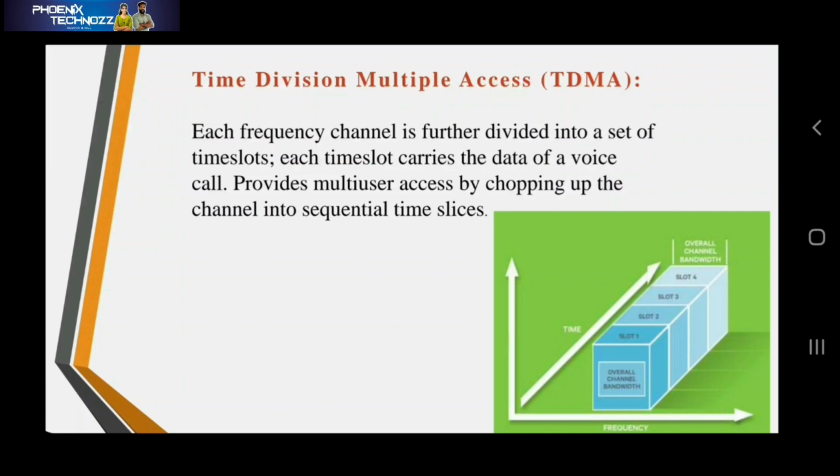So here also the multiple access interference can be avoided by allocating the communication resource in different time slots, but for the entire bandwidth. It was first used in satellite communication systems, and later in 2G cellular systems such as GSM technology. The problem with TDMA is that it requires accurate synchronization between the transmitter and the receiver. In multi-carrier systems, it is the main multiple access system.